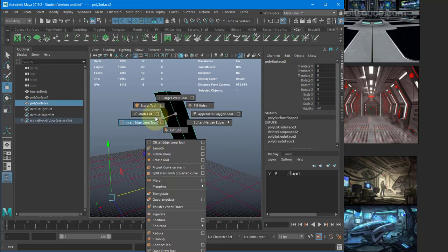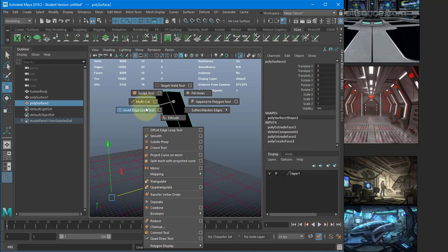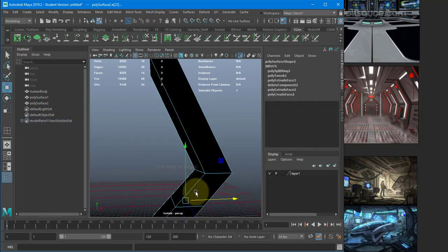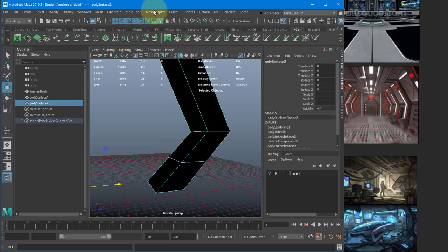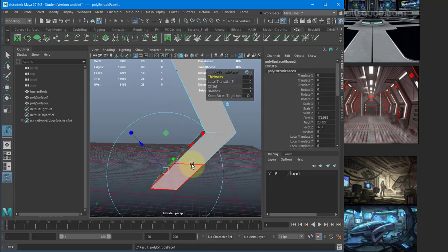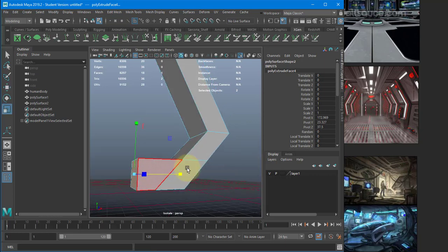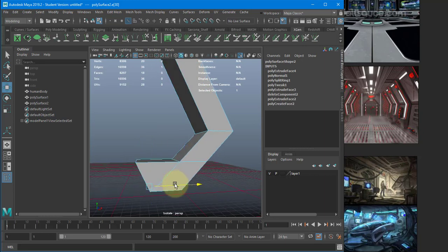Cool. So now I can add maybe an edge loop. Oops, not that. An edge loop right here. Let me grab this face. All right, this is black. I'm going to reverse it. There we go. Now grab the faces. There we go. Extrude this, move it forward, flatten it out. Maybe grab this edge and just shuffle that back. That's good.